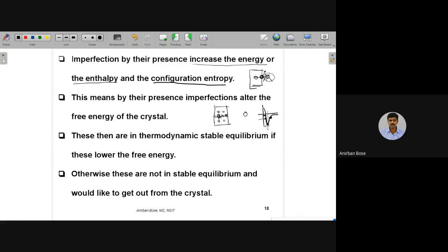So if that is another species, then it is important to note that there are certain atomic sites within a material, and suppose there are N atomic sites, but out of them a few atoms are missing, like vacancies. So let us consider there are n atoms which are not there. This is definitely a kind of imperfection, because some of the atomic sites do not have any atom. This is a kind of crystal imperfection. In that imperfection, you can understand the atomic arrangement: out of these N atomic sites, only n are vacant.